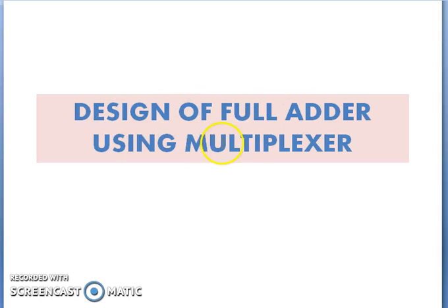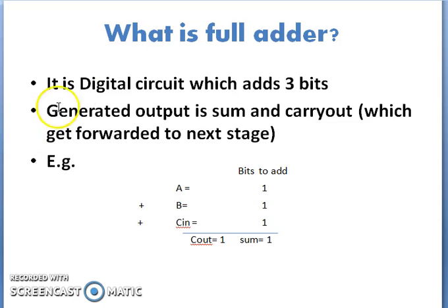Design of full adder using multiplexer. Already we studied what is multiplexer and how to implement logic gates using multiplexer. Now full adder. Full adder is a digital circuit which adds 3 bits.